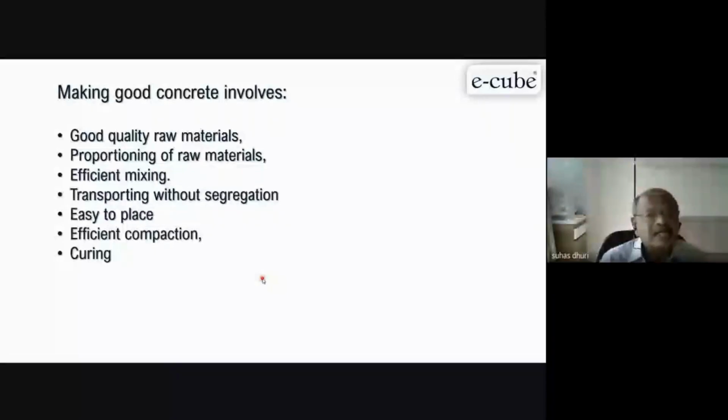And then we start repairing the concrete at the initial stage itself. That is not a good concrete technologist's role. So the concrete technologist has the freedom to change the proportion as the material changes its properties. The source is the same, but the properties are changing, like your particle size distribution has changed, the shape of the material has changed. We'll discuss this in detail later on, how they are affecting the properties of the concrete.